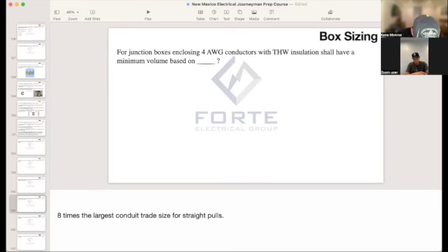And you go through there and you start reading it and it says equivalent of three-phase load on your minimum size feeders required for service equipment to meter banks for 20 dwelling units with 10 ranges. And you see the equivalent three-phase load is 54,500 VA. Yes, sir.